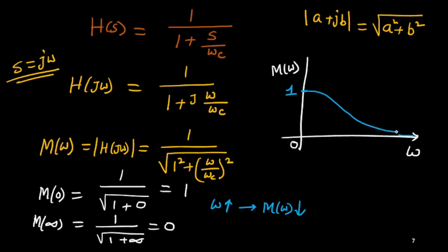Okay, freely we can draw these things. So this is the plot for M of omega for this RC filter. You can see that it is not an ideal low pass filter, but it is very close to that kind of shape. Thus it's a practical low pass filter.